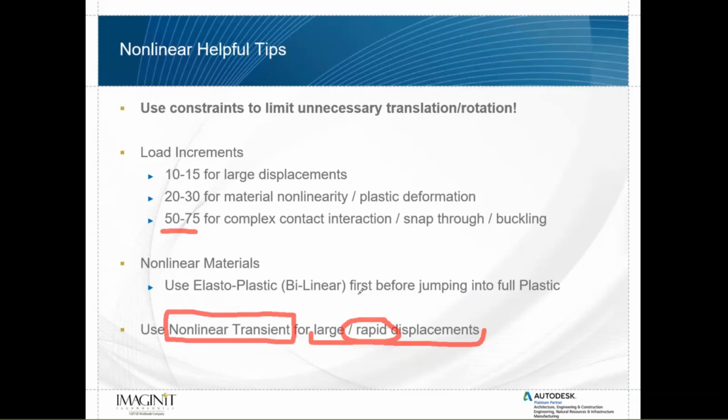So just keep in mind when you have those large, quick displacements, consider jumping over to nonlinear transient and looking at it in a time domain.